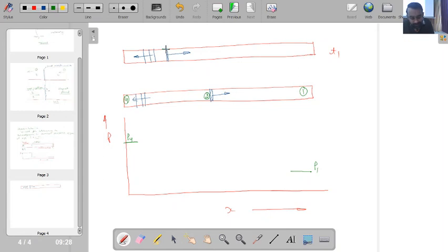Another important point: when I have only one-dimensional flow, when this shock wave is moving, behind the shock wave it will also be imparting certain motion to the stagnant gas, and that gas will also try to move towards the shock wave. So the fluid in the driving section will keep on moving towards the driven side.